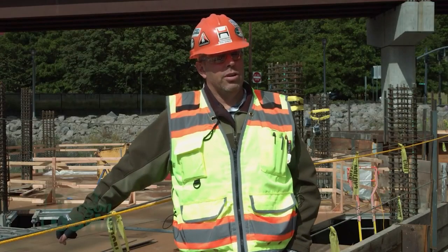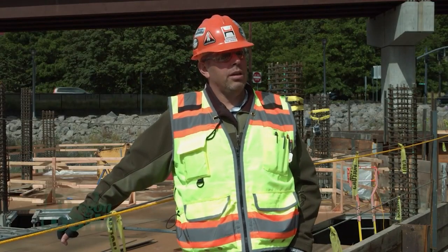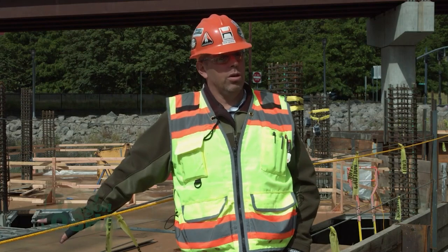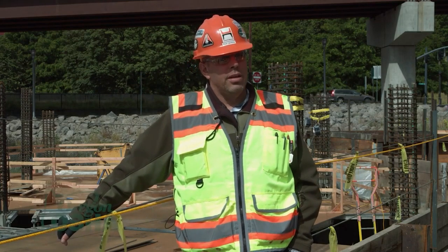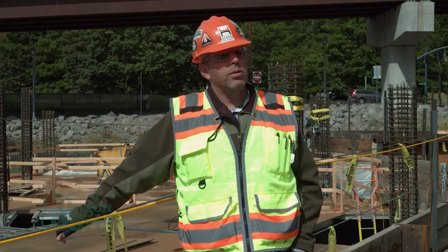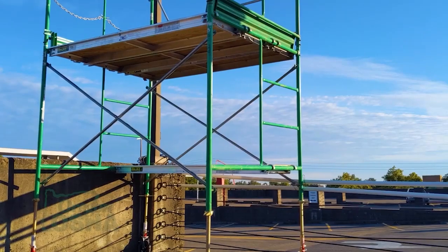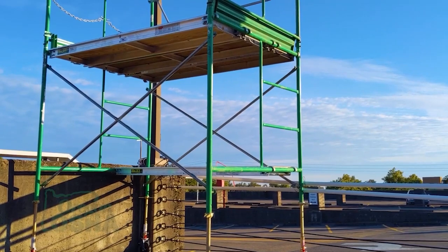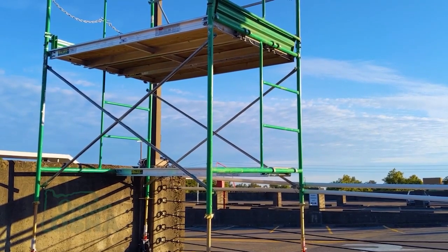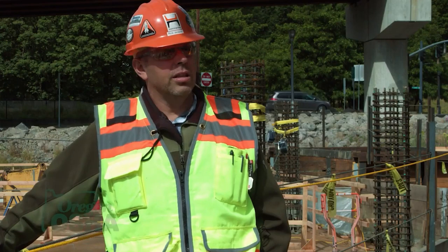Some common mishaps on scaffolding, planking. You need to make sure that you're not using dimensional lumber for the planking, that you're using actual OSHA approved planking, that your planking has a proper overlap from plank to plank and from scaffold bay to scaffold bay. Fully cross-braced systems, that on conventional scaffolding all your cross braces are in everywhere on the system.